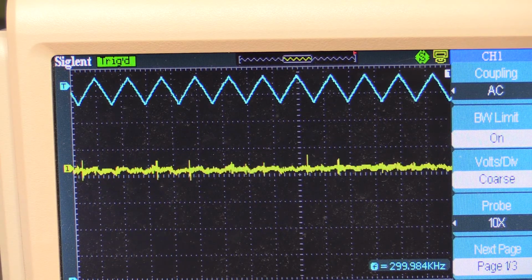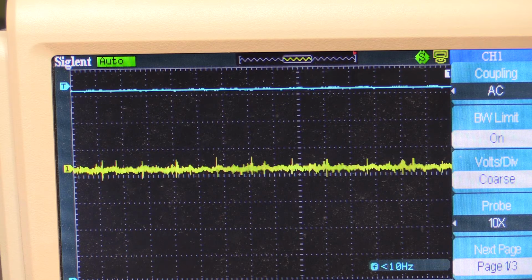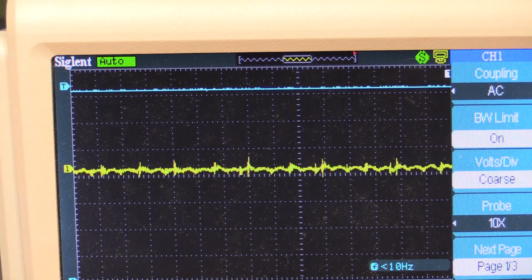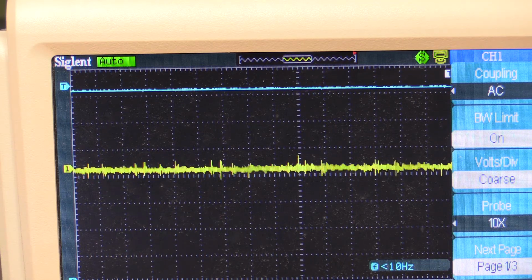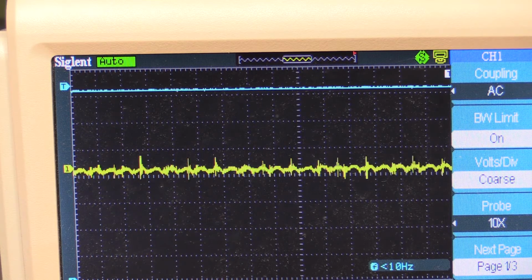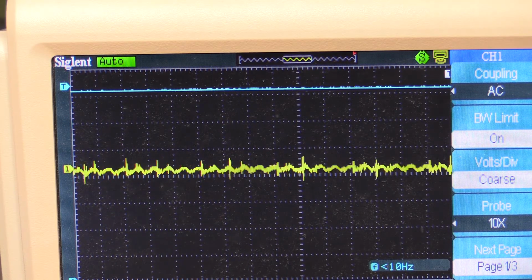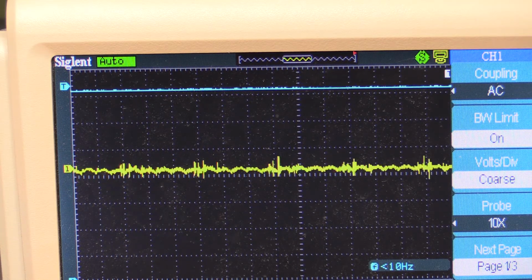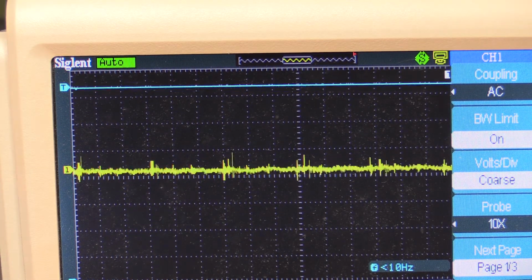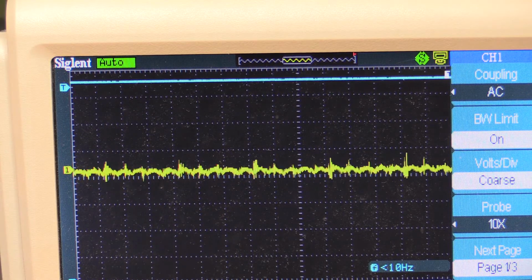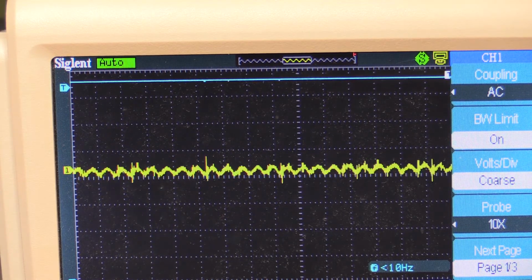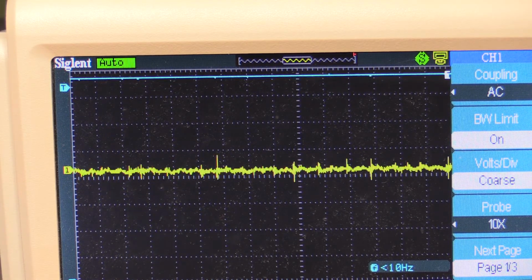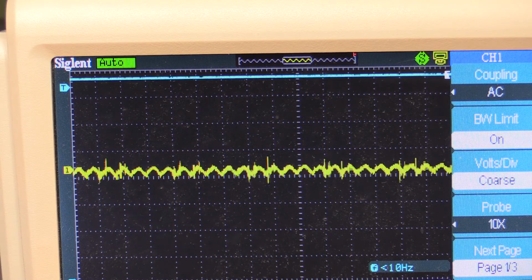waveform generator back to a DC output, which is what I've just done, as you can see there, it's now sitting at 3.617. So if I up this to read 3 amps, so 3.88 volts. Alright, so that's a 3 amp output.